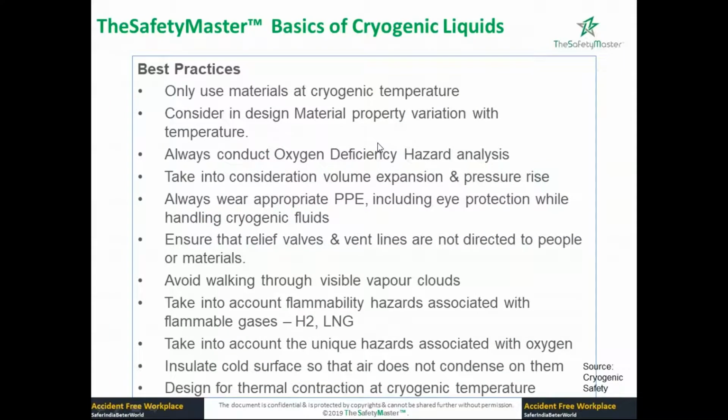And then you have to conduct or evaluate an oxygen deficiency hazard analysis, which is a prerequisite. It means if you want to give a permit or an authorization for a person to enter a zone, then you need to carry out this oxygen deficiency hazard analysis, and based on that you give the permit.